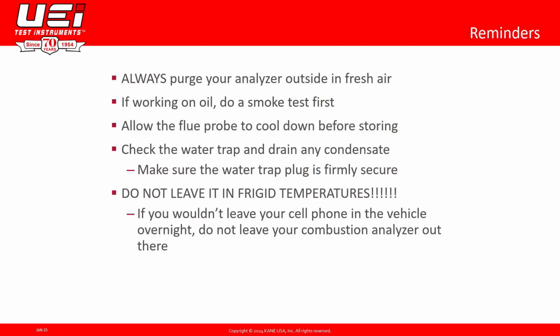So my rule of thumb, if you wouldn't leave your cell phone outside in your car overnight, don't leave the test instruments that are going to make you money in your vehicle overnight. And if for some reason you did happen to do that and you left it overnight, please, please, please make sure that you're allowing it to warm up to room temperature before using any of your products.